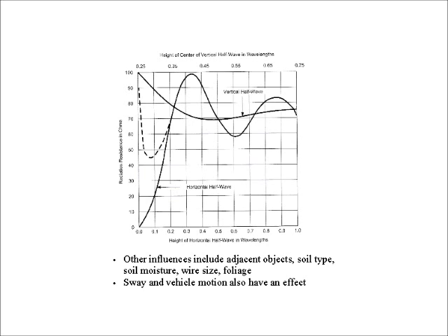So that's 1/10 of a wavelength, 2/10 of a wavelength, 3/10, 4/10, half a wavelength. If we go up here, you'll see that 70 ohms is here. Where those two cross, 72 ohms is the intrinsic impedance of a half-wave dipole, a half wavelength above ground.